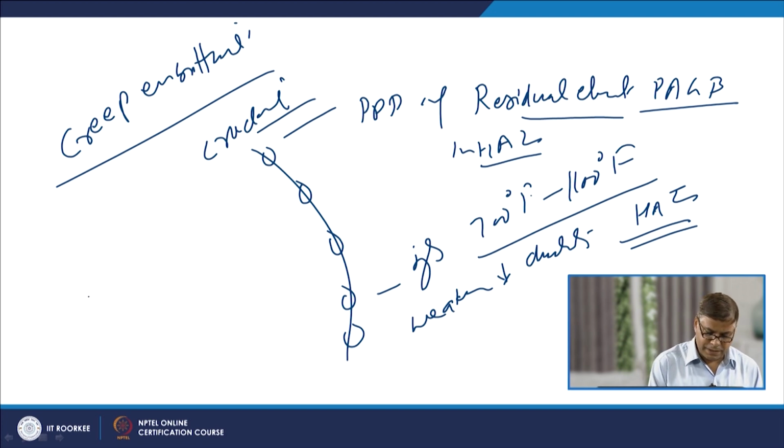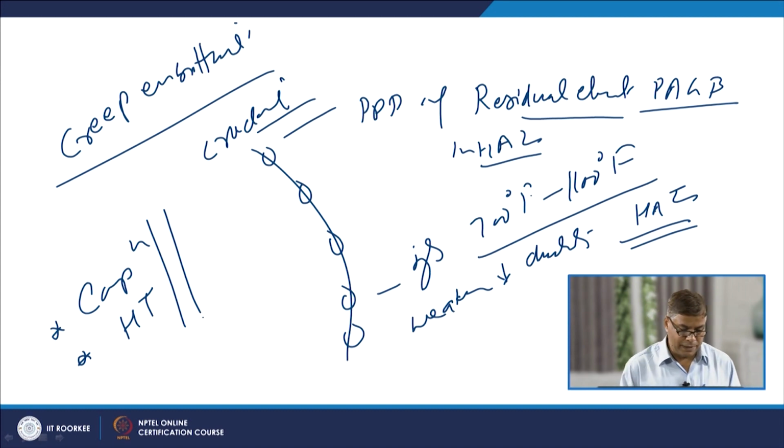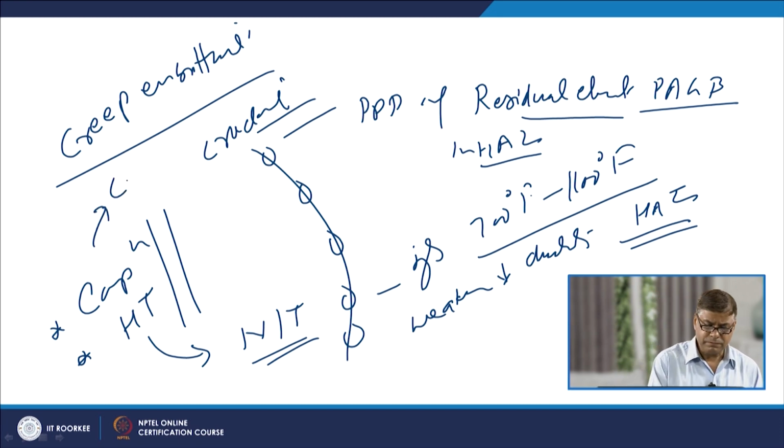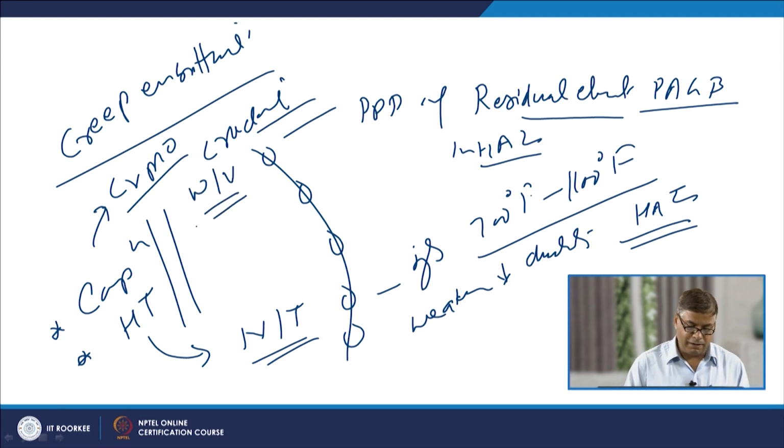and this kind of embrittlement is affected by the composition as well as the heat treatment condition of the plates which are being welded. Normally this problem is more severe when the weld joint is used in as welded condition, and some heat treatments like normalizing and tempering help to reduce this kind of embrittlement tendency. Similarly, there are a few compositions of the chromium molybdenum steels with the addition of tungsten and vanadium. They also help in reducing the creep embrittlement tendency of the chromium molybdenum steel weld joints.